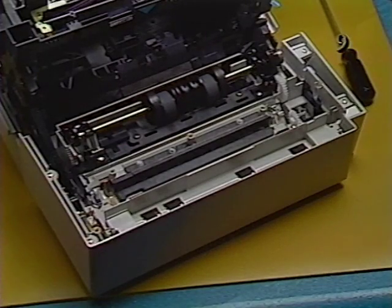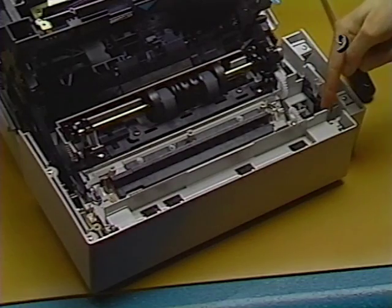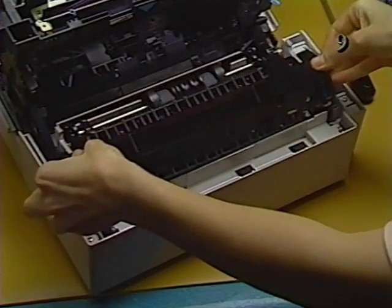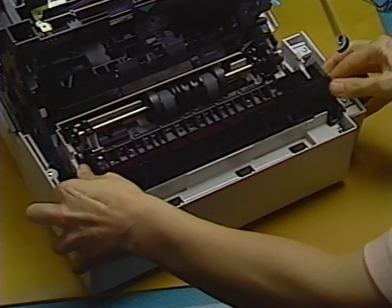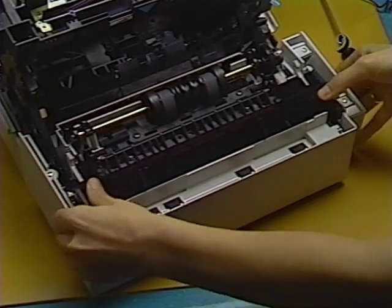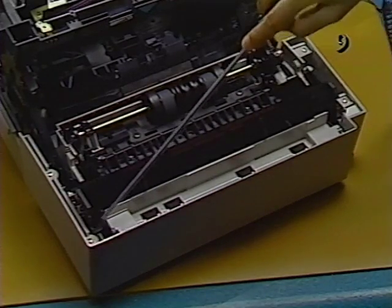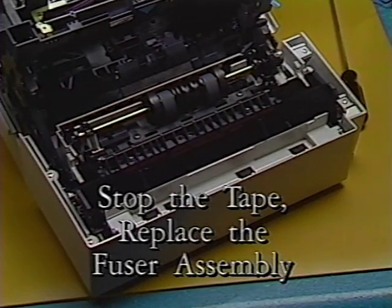First, making sure that the connectors at each end of the fuser assembly mate with the connector pins inside the printer. Lower the fuser assembly into position. Then replace the 5 fuser assembly screws. Stop the tape and replace the fuser assembly.